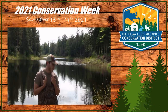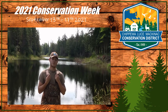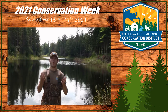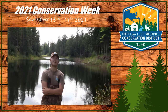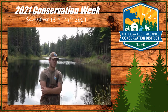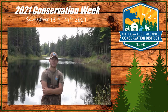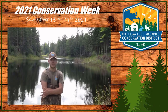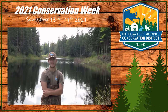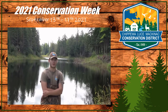that water body. The third parameter we're going to look at is specific conductivity. Specific conductivity is a measure of the water's ability to pass an electrical charge, and that is directly related to the ions in the water. Ions are typically in the form of salt, and we'll see high specific conductivity readings in areas where there's a lot of road salt runoff. In most systems, the range is about 150 to 1500. We want to see levels around 300. That's 300 to 350 is a good level for aquatic organisms.